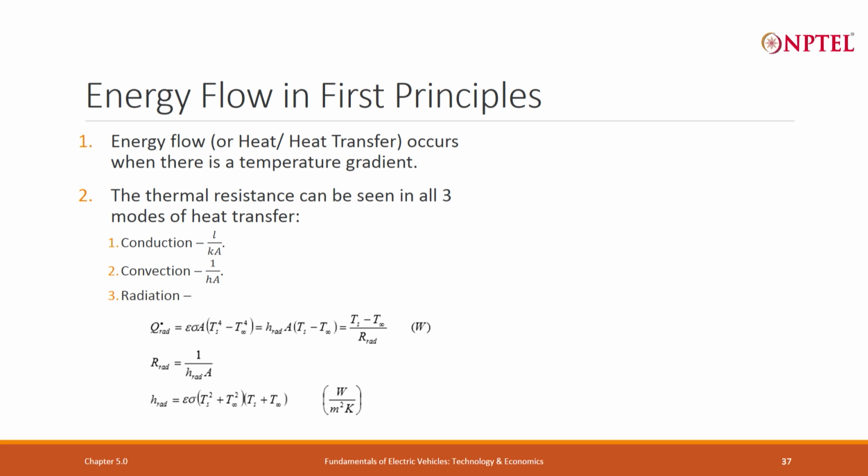Now, there is another mode known as convection. A lot of researchers or experts say there is no mode like convection. It is a combination of conduction. It is an extended part of conduction. We will not go into that. The convection is by bulk. Convection heat transfer happens because of the temperature gradient and bulk motion of the fluid. So, here the convection heat transfer is because of two materials. The temperature gradient comes from two different things. One might be a solid or liquid or something, the other would always be a fluid. Fluid means either liquid or gas.